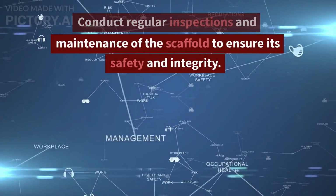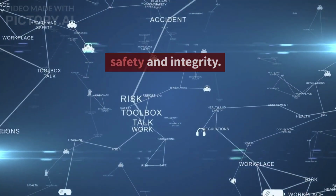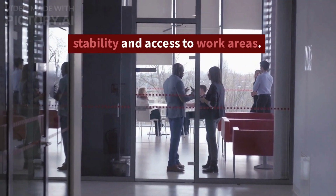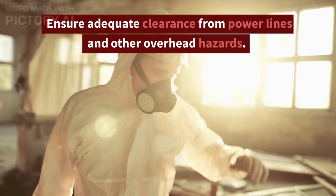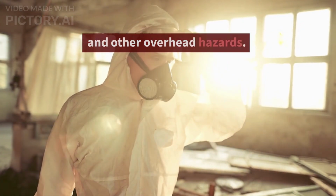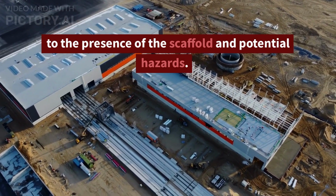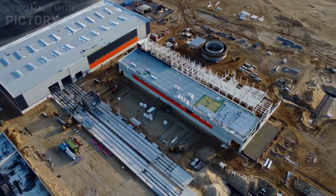Conduct regular inspections and maintenance of the scaffold to ensure its safety and integrity. Properly position the scaffold to ensure stability and access to work areas. Ensure adequate clearance from power lines and other overhead hazards. Use warning signs or barriers to alert others to the presence of the scaffold and potential hazards.